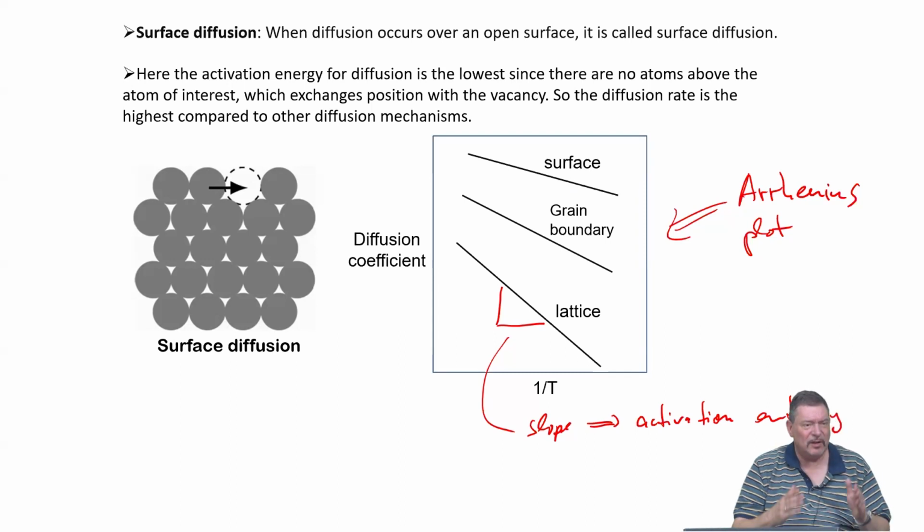Yeah, but let's say your diffusion zone, let's put it like this. In a scanning electron microscope, you can only, in cross-section maybe, get the average concentration of a certain element. So you can measure diffusion profiles. But the resolution by which you can do it is not sufficient to look at individual defects. So you will not see diffusion along a grain boundary. You will not see diffusion along a dislocation core.